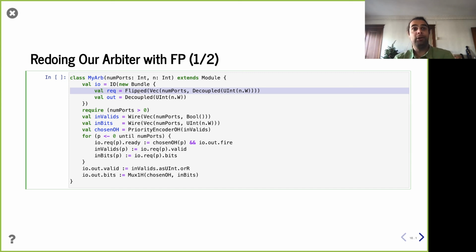They all perhaps make requests, and only one's going to come out the other end. We need to let the requesters know via ready-valid signaling that they succeeded. These requesters are sending a valid indicating that they're trying to make a request, and this component's going to respond with a ready to let them know that they actually won.